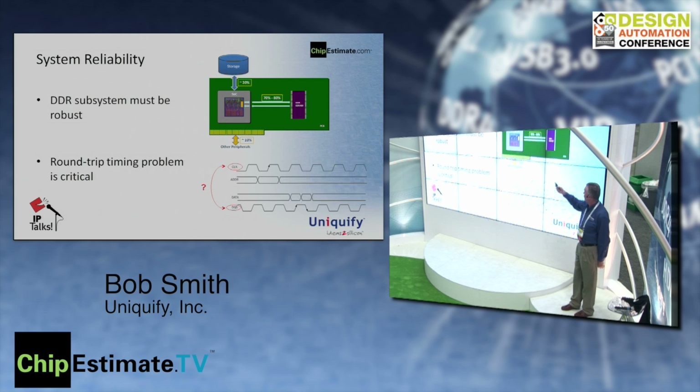And it turns out you would think, well, gee, isn't it all synchronous? Well, in reality, there is quite a bit of latency, and of course you're sending signals out over perhaps across a board or other substrate. You've got delays in the package itself. So when you're looking at this problem, what you're trying to figure out is how many clock cycles have gone by on my system clock since I issued the read, the latency, and what is the actual phase relationship of the edges.